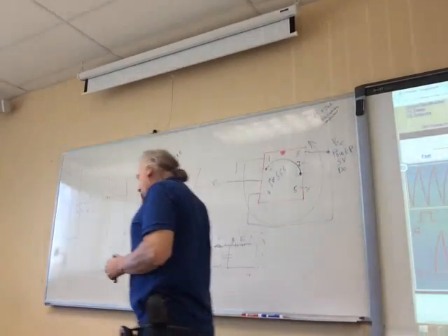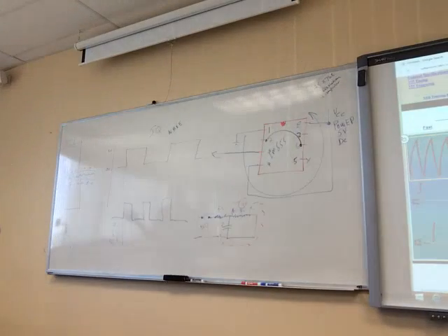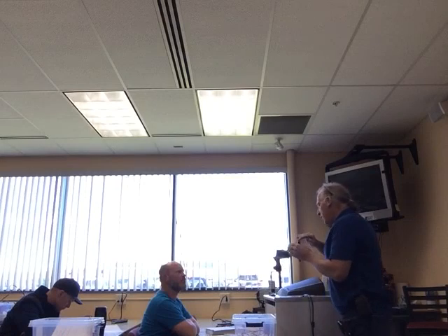And if we didn't use any calculus, we'd never be able to figure out where it actually ended up, fully charged. So you have to use a little calculus to look at the curve. So what they said is, okay, enough is enough. We don't want to wait around here 6 months for it to get all fully charged up. So we'll just say one time period is 1t, and that's 63%. So if it takes 5 minutes, okay, one time period, 63%. If it takes 1 second, that's the time period. You can calculate that.